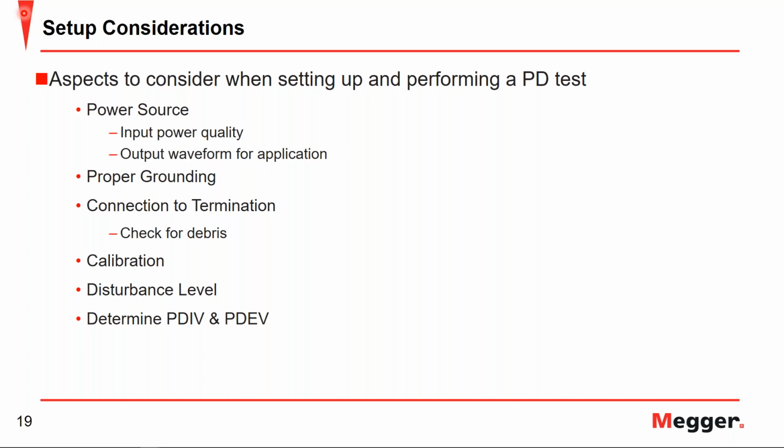The next is kind of the tricky one, where you may have inception voltage above operating and extinction voltage below operating. And what that means is whenever you do have that transient, you may incept that partial discharge, and once it settles back down to operating voltage, that partial discharge is going to continue to take place.